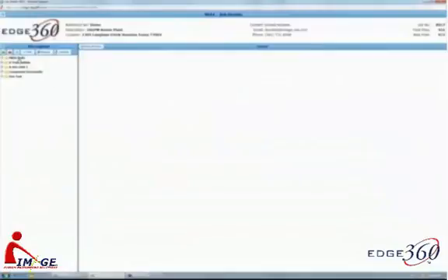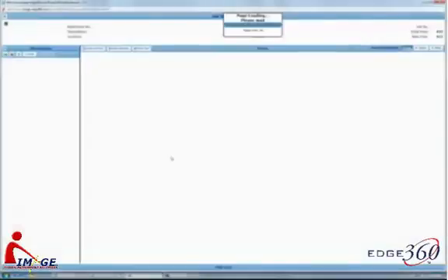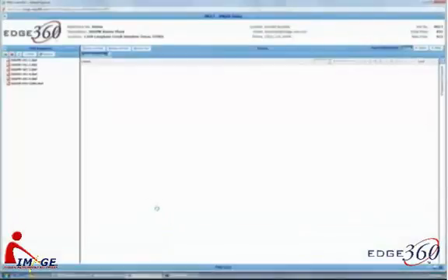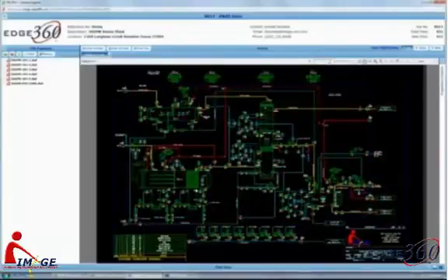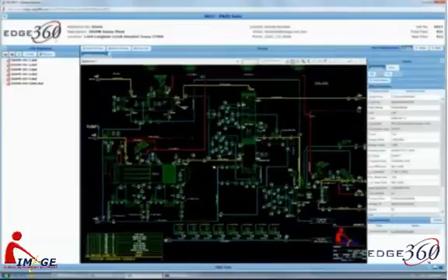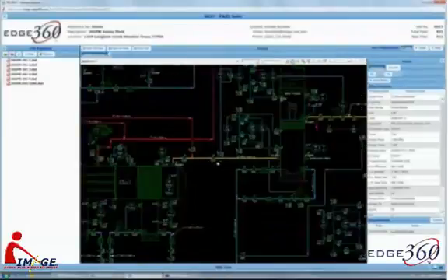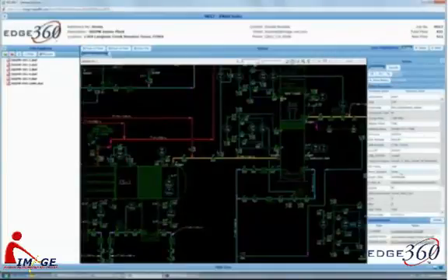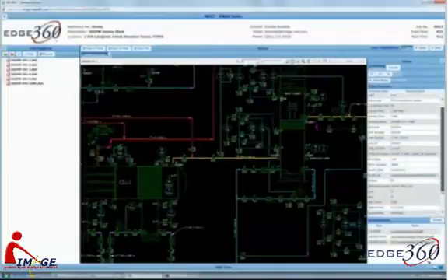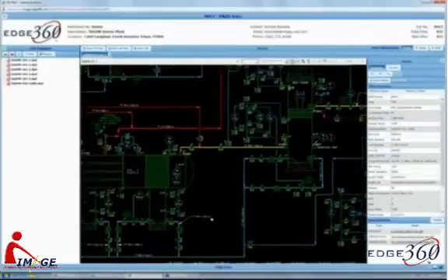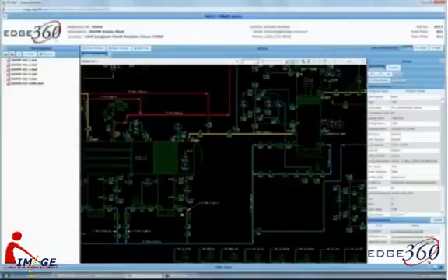I'm going to start out by going into the P&ID suite, and I'm going to open my first page of P&IDs. You can see there were several pages of P&IDs there. Now, this is not just a drawing, it's an intelligent P&ID. It's CADWorks, of course, but I can select on anything here. I can select, for instance, this valve, and all of my information from the P&ID database is shown over here. Any fields that have no properties populated are not going to show anything.